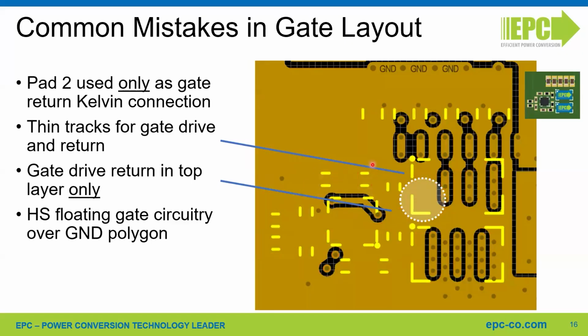This is increasing the capacitance between the gate and the ground, which in AC is connected to the drain of the high side FET by the bypass capacitor. So basically, this superimposition of the gate circuit on the ground for the high side device is increasing the drain to gate capacitance, and it can also cause parasitic oscillation of the FET because of this increased capacitance.